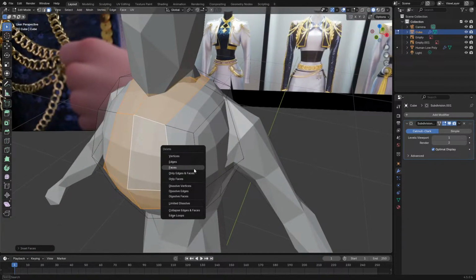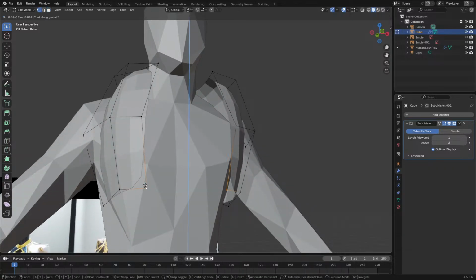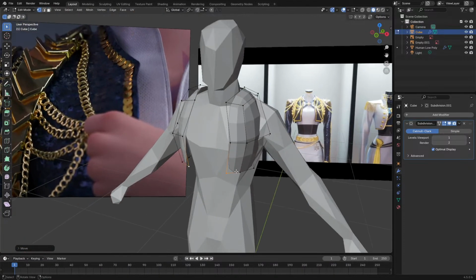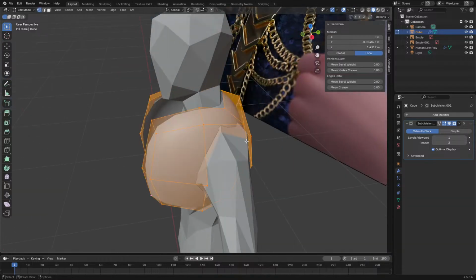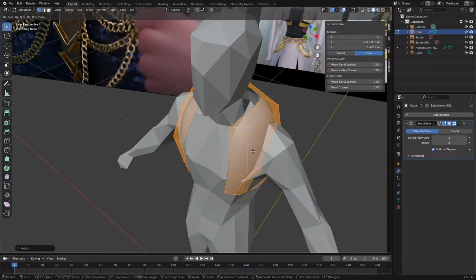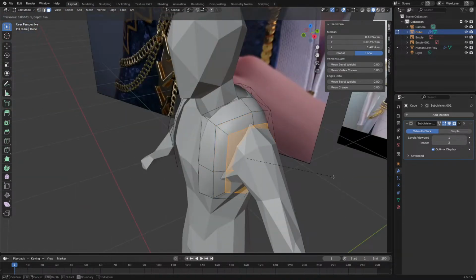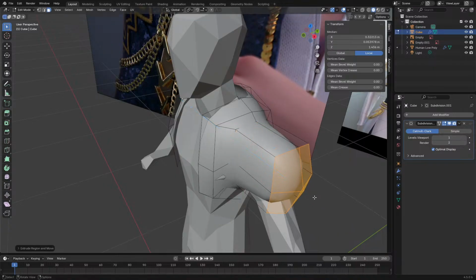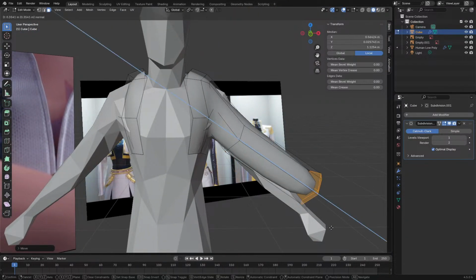We can just do that, delete you and you, then we're back. Bring this down, and how does that look there? Okay, that's just a harsh corner, so I could just select both of these, or just select the vertices, and then set the vertex crease, and we can see that works quite well. Let's go and move this. I'm not going to shrink wrap it to the body, even though I probably should. Let's get this, and I should mirror it, so I'll just do this now, because that's what I'm going to end up doing.